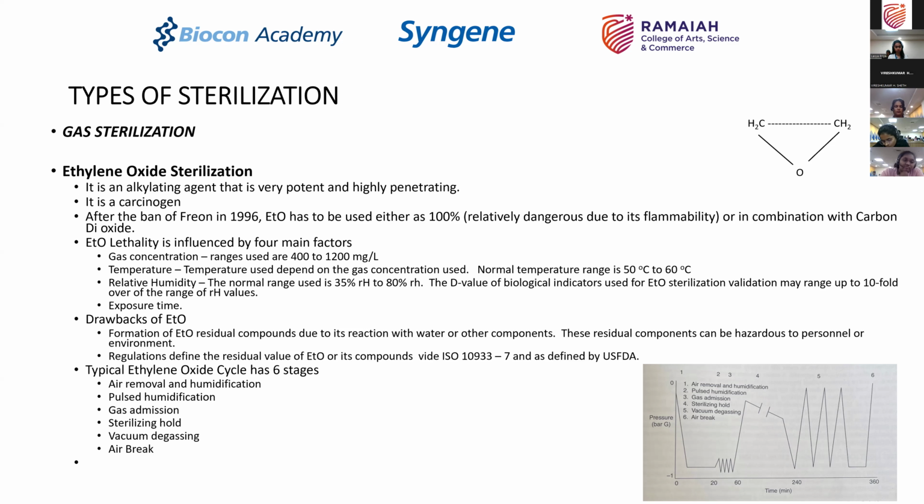The biggest problem of ethylene oxide is that it is reactive. It tends to form compounds due to the presence of moisture. And then there are other components, like if you're sterilizing, let's say, husk, or any powder, the chemical composition of the powder interacting with the water and the ethylene oxide can form residues of ethylene oxide, which can be hazardous to people and the environment.